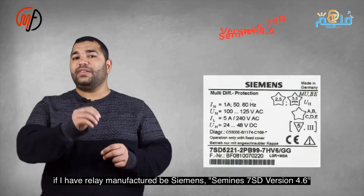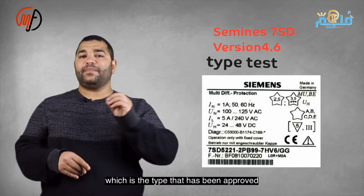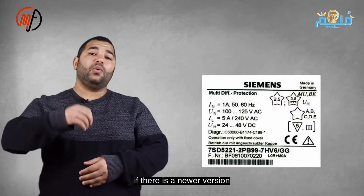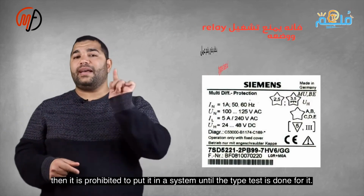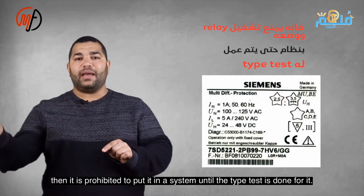If I have a relay from Siemens, model 7SD version 4.6, which is the one that underwent type testing, that is the one that gets approved and placed on the approved list. If there is a newer version, the operation of that relay is prohibited, and it cannot be integrated into the system until it undergoes type testing again.